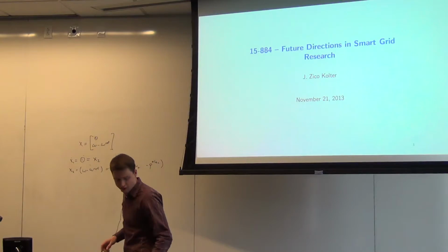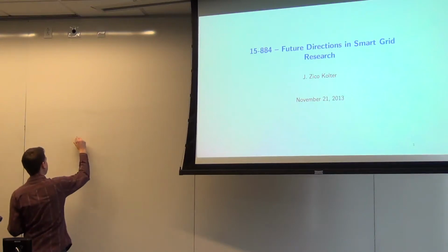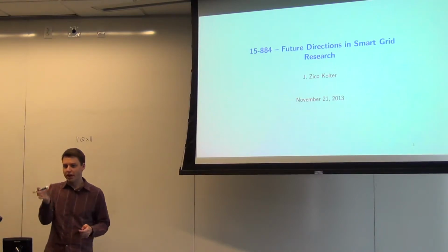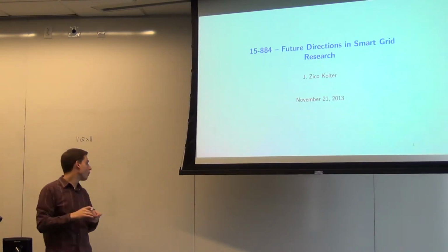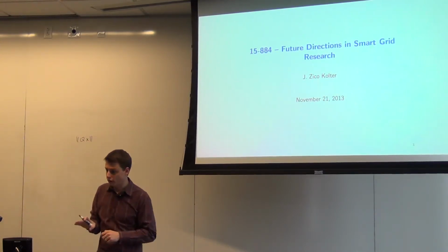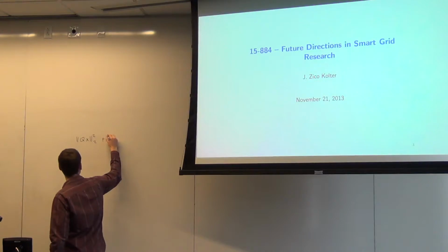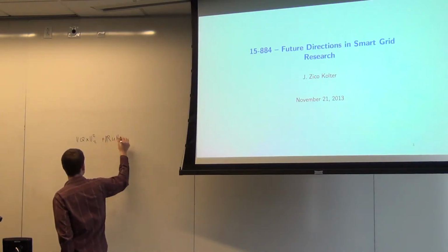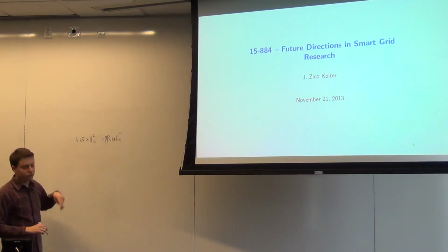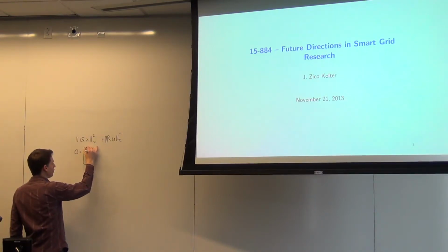Let me clarify what I mean by that. Your cost is something like x transpose Q x, and that works because, again, our desired angle is 0 in this case, and the desired deviation for angular velocity is also 0, right? You want to keep those both at 0. So this is our cost on the states, and we also have one on the control inputs. The nice thing is that I typically will choose Q to be diagonal. So Q equals some diagonal matrix here, and I'll usually just start with the identity, say.